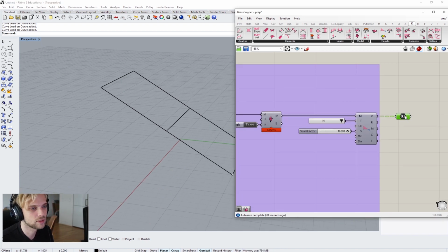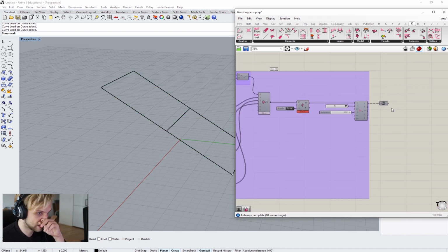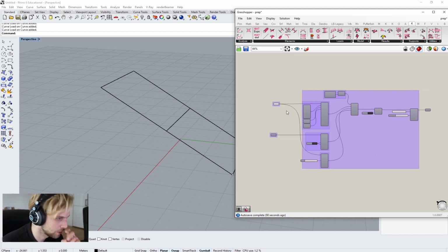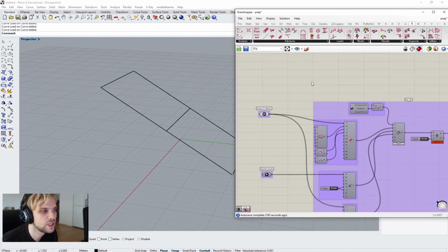we have values, right? And we have our beams, and I need to colorize these beams, like these curves, according to these values, right? So the curves that have a lot of stress need to have color red. Curves that don't have a lot of stress need to have color green, right? How do we do that? Well, first of all, the curves need to be three-dimensional, right? They need to be a mesh.